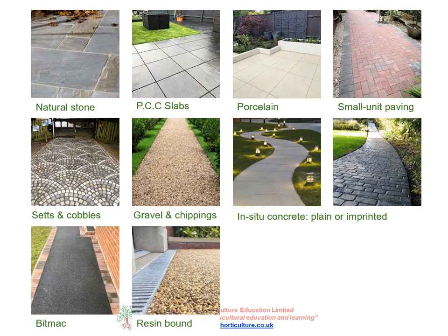We mentioned previously gravel and chippings have the disadvantage that they can kick around and get into lawns and borders. An option here may be to have resin-bound gravel, where the gravel or aggregate is mixed with the resin to form a solid surface. This gives the look of gravel or chippings, but without the disadvantage of materials kicking around. Modern versions of resin-bound materials can also be permeable, allowing water to drain through.